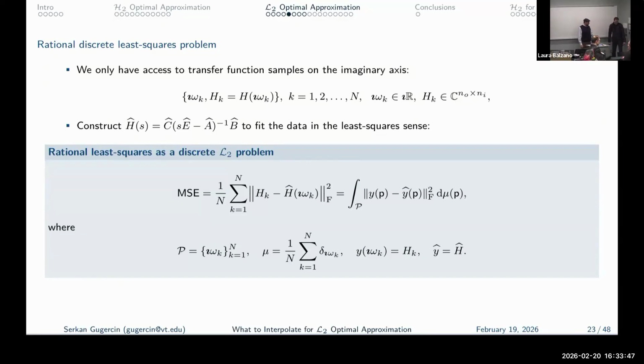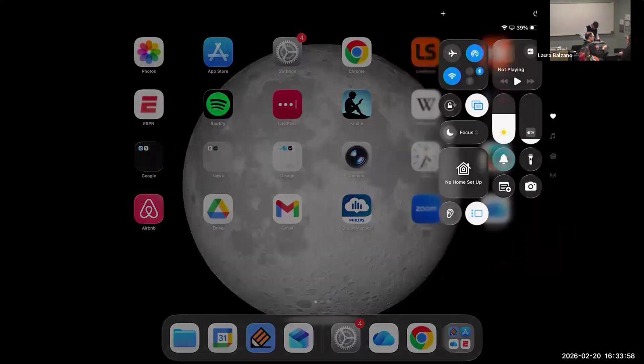Yeah, we were talking about it. When you do control, you actually don't care if the model is wrong at low frequencies. In fact, if it's a model that's slightly unstable versus slightly stable, if you did time domain simulations, they're going to diverge over time and be completely broken. But a controller that stabilizes one is almost surely going to stabilize the other, and there's formal theory of that. So you don't actually care about these long time scale differences. And you also don't care about differences at very high frequencies, because usually there's a middle range where the model matters.